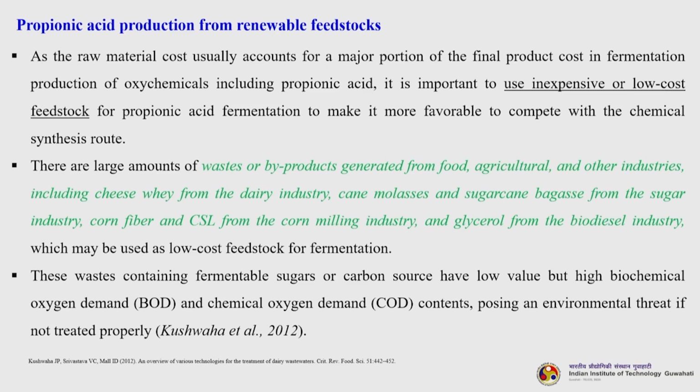There are large amounts of wastes or byproducts generated from food, agricultural and other industries including cheese whey from the dairy industry, cane molasses and sugar cane bagasse from the sugar industry, corn fiber and CSL, corn steep liquor basically, okay, from the corn milling industry and glycerol from the biodiesel industry, which may be used as low cost feedstock for fermentation processes. Now, these wastes containing fermentable sugars or carbon sources have low value, but high biochemical oxygen demand and chemical oxygen demand, the BOD and COD, posing an environmental threat if they are not treated properly. So, it is something you can say that waste to value added products.